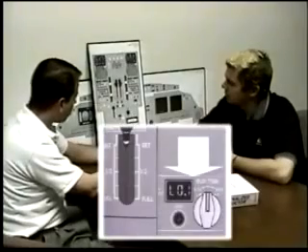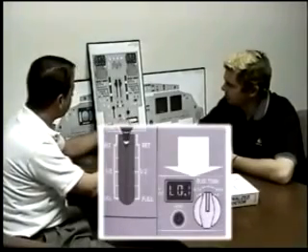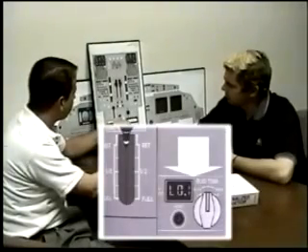Rudder trim. The LCD readout will display rudder trim whether the autopilot's engaged or you're manually selecting rudder trim. Tell me how much rudder trim you can command manually versus the autopilot. Manually, we can command about 1 degree per second. In the A320, we get 20 degrees, so it takes approximately 20 seconds to get that. In an engine out situation, it's between 17 and 20 degrees we want anyway, so we might as well just run the trim over there.